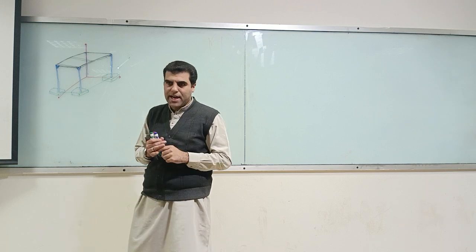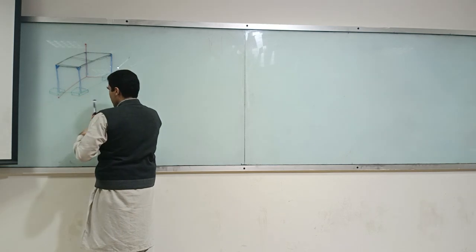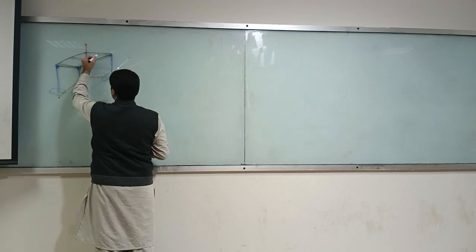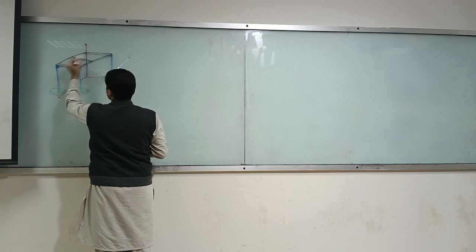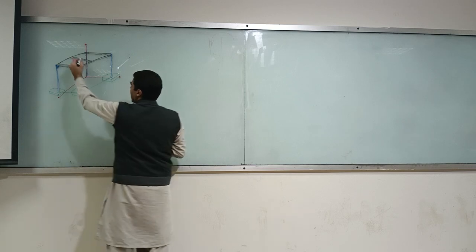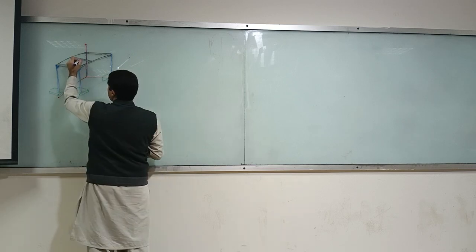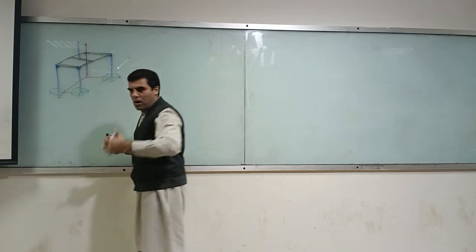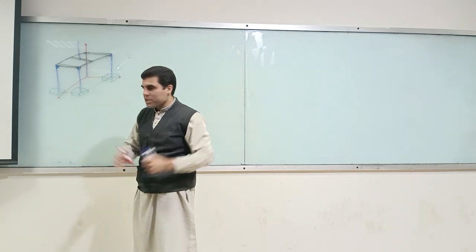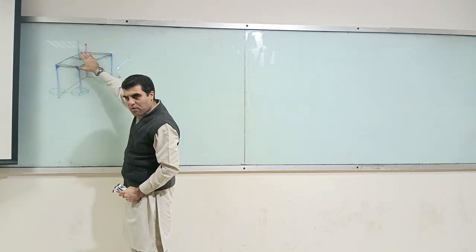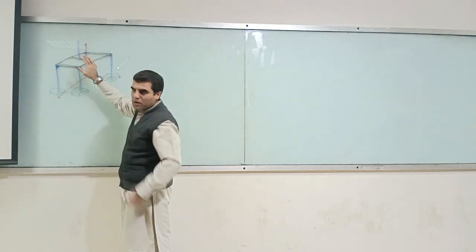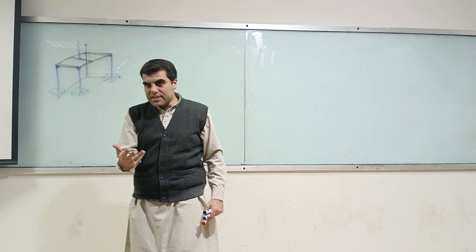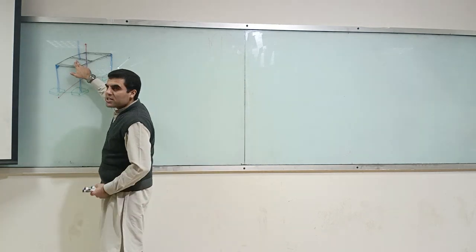That is one assumption, or you can have an actual load applied on that structure. For example, if I have three beams, which I am showing with double lines, so we have got three beams on this frame. I can have another column resting on this beam. This can be a column of another structure, a supporting structure. Imagine this is our classroom, and there is another classroom which has got a column in the middle. Normally you wouldn't provide a column in the middle, but imagine you have another structure which has got a column in the middle. So this is a concentrated load which is being applied onto your structure.